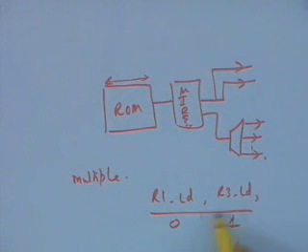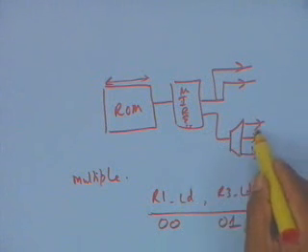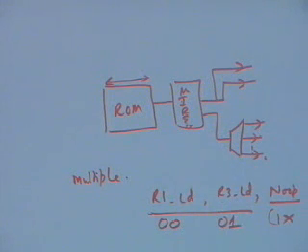But as I said, when we are merging these two, we have to have a no-op. So we can say 0, 0, 0, 1 and let us say 1x. We can have this, and based on this 1, we decide which one. So this decoder will take these two inputs and generate the R1 load and R3 load. So whenever we have a set of control signals.